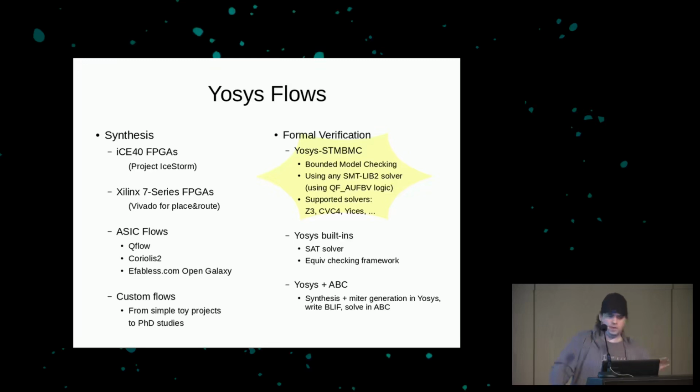Or you can use Yosys just as a front end to convert your design into something that can be understood by other tools. For example, you could use Yosys as a front end and combine it with ABC and do verification in ABC. But the thing I'll be talking about is the first one, Yosys SMTBMC, a framework for bounded model check and temporal induction enabled by Yosys.